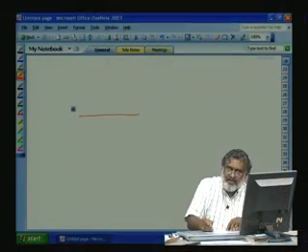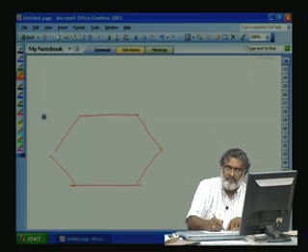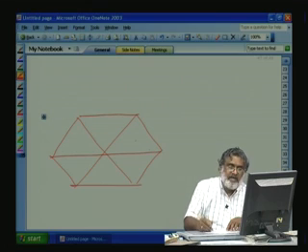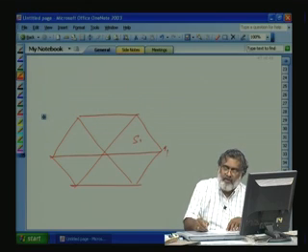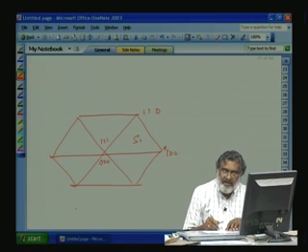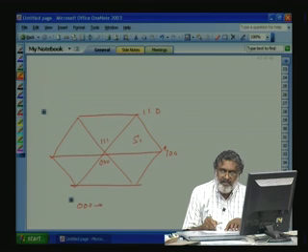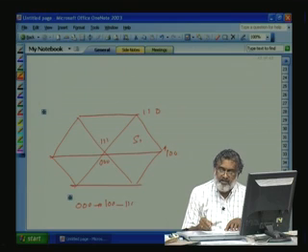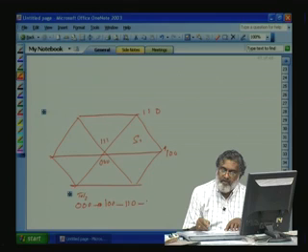So, from the controller, if you know alpha beta, we can easily transform alpha beta into ABC. Then once you fix the TS for a particular inverter switching, let us say 1 kilohertz sampling, it will be 1 millisecond. But if you see here in a sector, this is our hexagon. Let us say S1, it goes from 100 to 110, then 111, 000. So, in a sampling period, we start from 000, next it will go to 100, then 110, then 111 for T0 by 2. This is one sampling period.